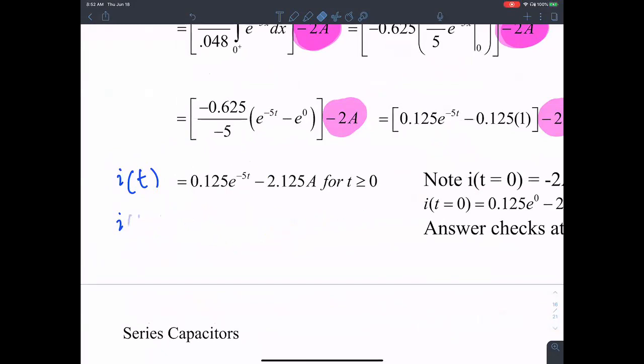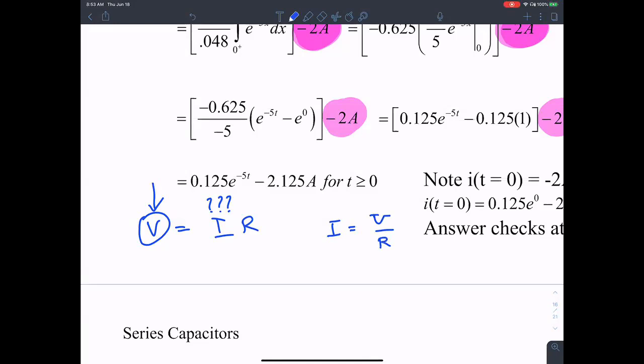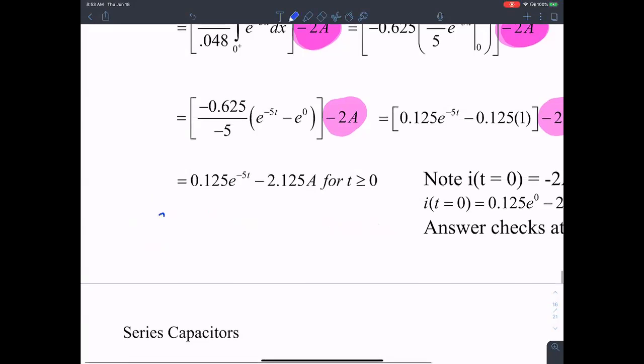So all you had to do was apply, just like the question is similar to V is Ohm's law. If V is given and you are expected to find I in a resistance, what would you do? You would simply divide the voltage over the resistance, an application of Ohm's law to get the current. Similarly, in this problem, V is L di/dt.